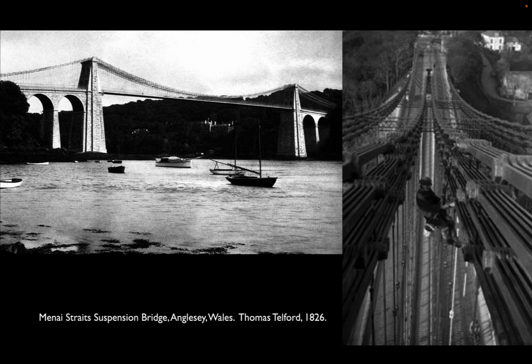They go over saddles on top of the towers, and they're connected to backspans. And you can see that there are cables that then go into anchorages in the land, and the anchorages basically hold the cables and allow them to develop a huge amount of tensile force within them. You can see that the approach decks have cables running down to them that are basically holding the main cable down, making it maintain its shape. And this allows you then to have a balanced load on the other side, which is the weight of the deck rolling between the two compression towers.